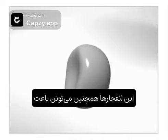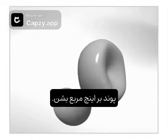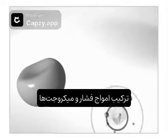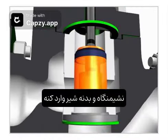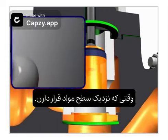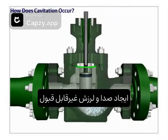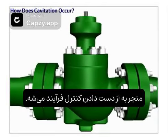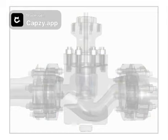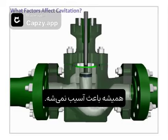These implosions can also cause local pressure waves of up to 100,000 pounds per square inch. The combination of pressure waves and microjets can cause severe damage to the valve plug, seat, and body when they're located near the material surface. Cavitation can also cause unacceptable noise and vibration that reduce efficiency or lead to loss of process control. Even though cavitation occurs, it doesn't always cause damage.